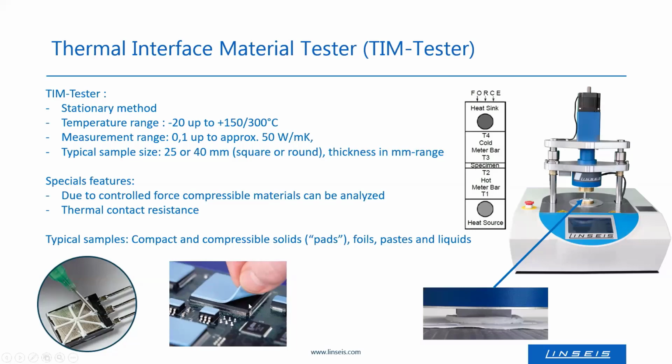This should be connected to a cooler, and if you put two solids, one on top of the other, the heat transfer will be poor. And to increase this heat transfer, you can use such thermal interface materials, which can be compressible solids, like in these examples, or pastes, like in the two other examples.